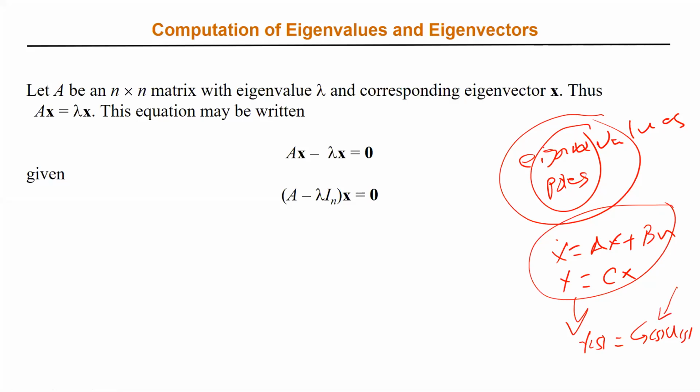There is a possibility that from the input-output point of view, through my transfer function, the system is stable, but if I take the stability of the state space, the system is unstable. There is one possibility. That's why the eigenvalues will give you more information about the system. What will happen at a certain time is that there will be a pole-zero cancellation.